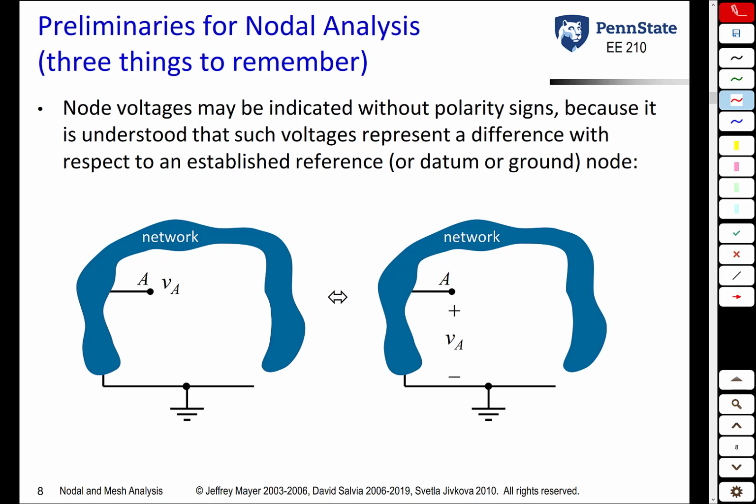Now that we've discussed single loop circuits and single node pair circuits, we're going to take those concepts and apply them to the more complicated and more general nodal analysis and mesh analysis algorithms. So we're going to talk about nodal analysis first. In nodal analysis, we're basically going to have voltage variables, and we're going to use Kirchhoff's current law to solve. So it's going to be an extension of the single node pair circuit approach.